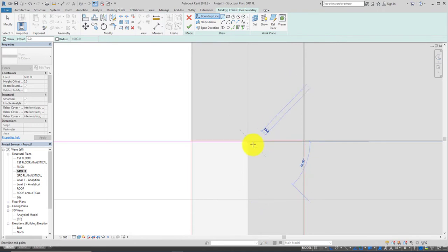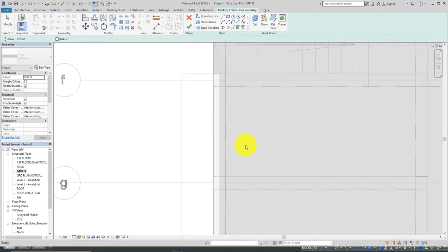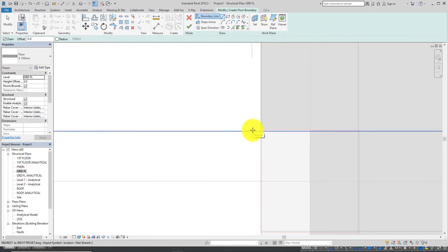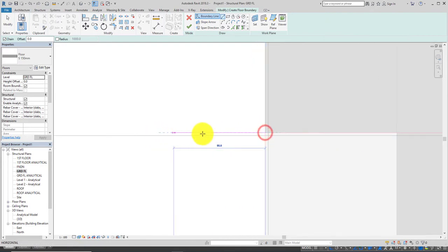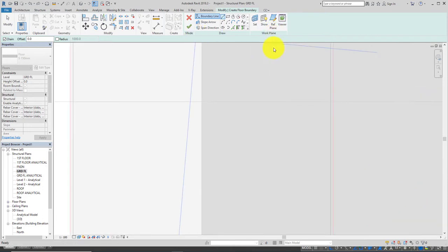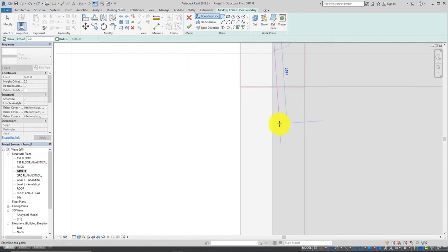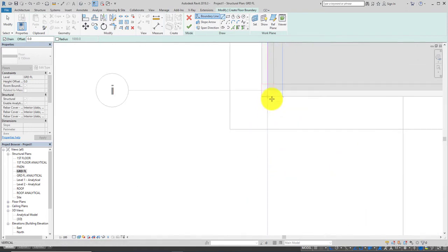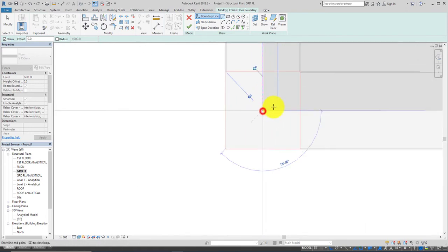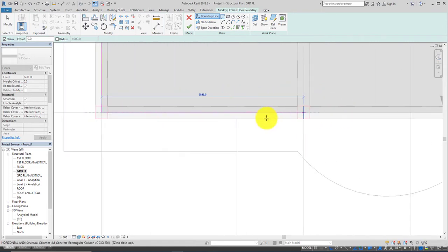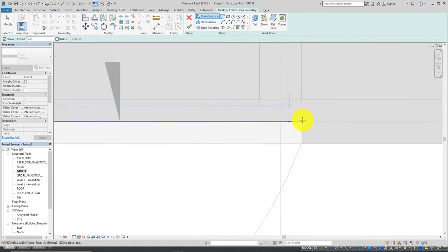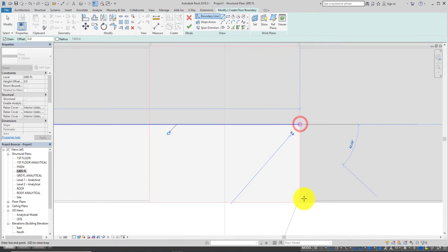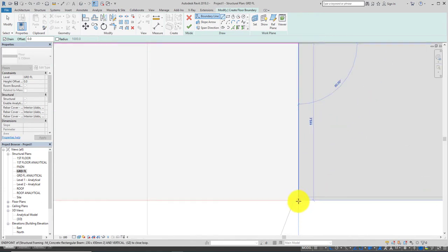So that we'll be able to prevent the overlapping. You see it's entering into this wall, so we say Ctrl Z. These are things you should take note of, otherwise Revit will tell you your project is overlapping. So we have this. Let's ensure it's not overlapping. The walls are not overlapping, if not you will receive your error sign. So we have to this point. Yes, we'll come in up to this point. Finally to this point,